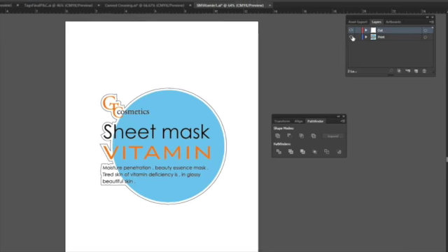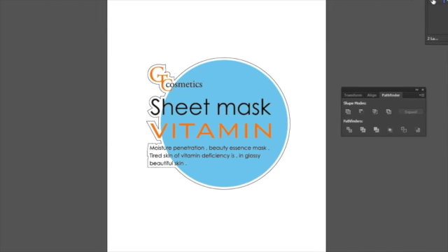In order for the cutter to follow the cut path accurately, registration marks have to be placed on the design. Registration marks provide information to the cutter for precise cutting. Once the marks are scanned, the cutter determines aspects such as the starting point, angle, and any distortions.